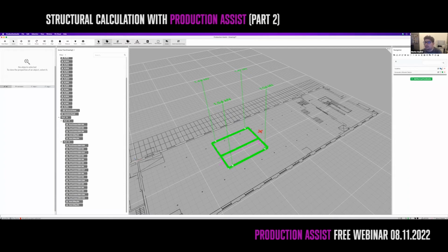You can switch this by just clicking on here, which will increase the loads on the hoist, because now also for the supports, the safety factors are considered. Changing this back actually brings back the results that you want to see in order to prove if a hoist is good or not. Right now, this truss is on the ground.